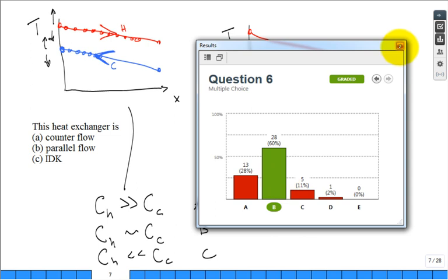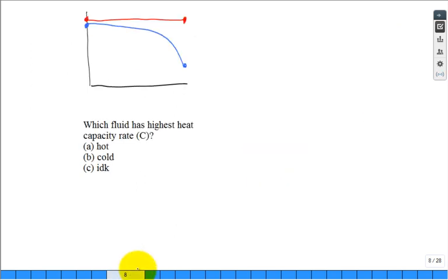And so this brings in this concept. Last time we talked about maybe this is a direction for the hot fluid, this is a direction for the cold fluid, right? And we talked about if the mass flow rate of the hot fluid went way up, then the heat capacity rate of the hot fluid would be large, and you wouldn't think that the hot would change much in the way of its temperature change as it goes through. It's like the concept of a thermal reservoir way back in Thermo 1.